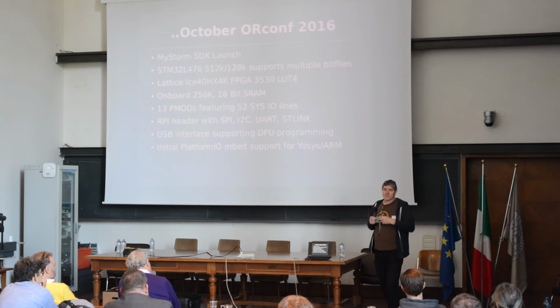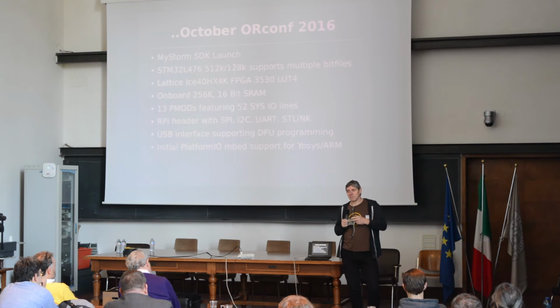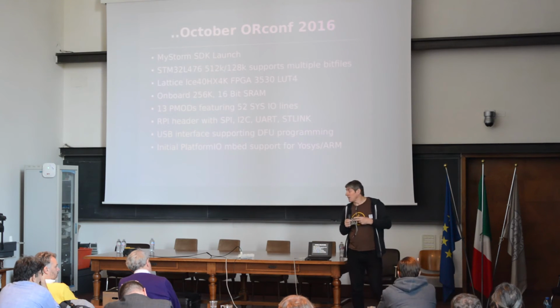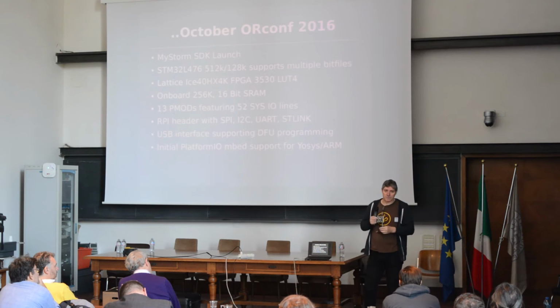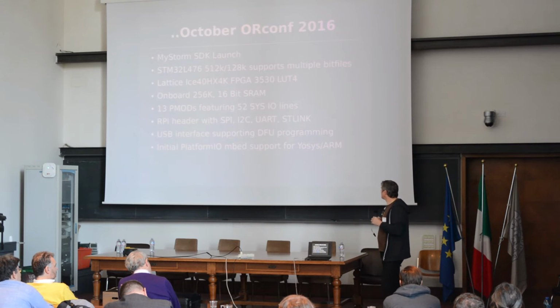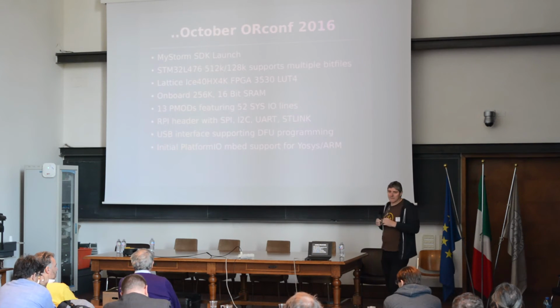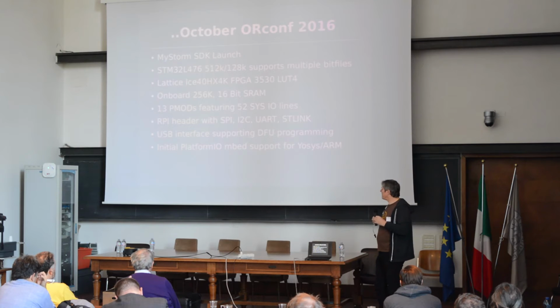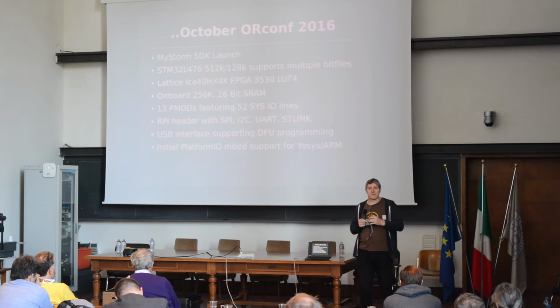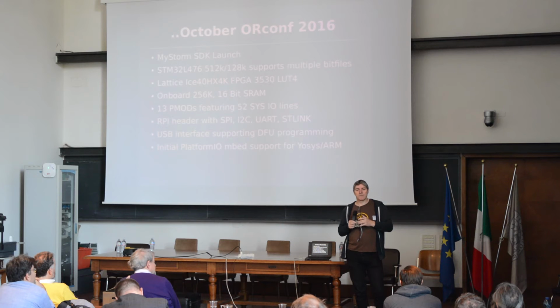This 476 also has a DFU bootloader installed by default, and we intend using that as a means of getting the binaries up and down to the device. We haven't finished the work on that at the moment, which is why I'm still using the ST-Link. As of yesterday, I managed to get some basic MPEG support for the 476. We had the code that we wrote for the 103, but we couldn't get that working with the 476. That was using the STM libraries.